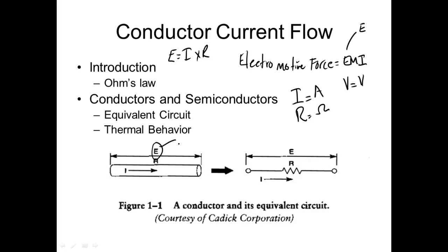So here they're saying, okay, anytime I put current through a conductor, that conductor is going to drop some voltage. And why is that? Because all conductors have an R. Now it's not much. It's usually rated in so many ohms per 1,000 feet, but it's still R. If I put current through an R, it's going to drop a voltage. And if it drops a voltage, it's going to release power. So these conductors get warm. Right? You understand that?